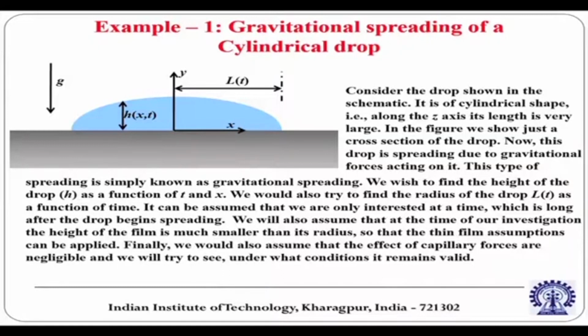Finally, we would also assume that the effect of capillary forces is negligible. It is just for demonstrating a problem, that is what I intend to tell you, because if you include the effect of capillary force, equations may become intractable within the scope of a class coursework. But inclusion of surface tension forces, surface tension gradients, disjoining pressures, these are some of the very standard things that we commonly do in research, and even in advanced texts, that is what is commonly used. But just purely to demonstrate how to solve the thin film equation, I will consider that gravity is the dominating parameter.